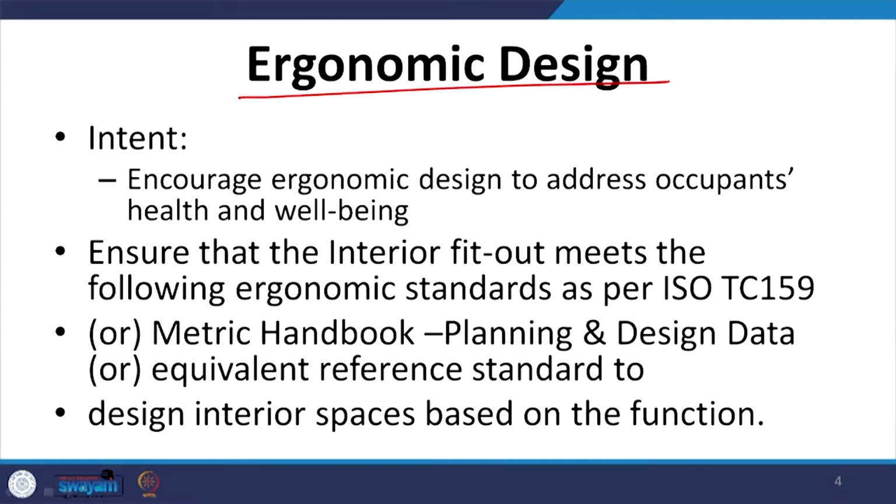The next very important thing is using a product which is ergonomically designed. An eco-certified product may not necessarily be ergonomically designed. This ergonomic design is required in order to address occupants' health and well-being. Consider that in an office, a person has to sit on his chair for 8 hours every day. If it is not ergonomically designed, it is bound to give health problems to the occupant later on. A lot of office occupants these days complain even when the air quality is good, even when they are inhaling the best quality air, it is thermally comfortable, it is visually comfortable, even then people complain of backaches, shoulder problems, and problems in their hands because of their sitting posture.